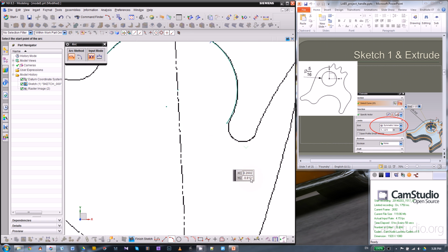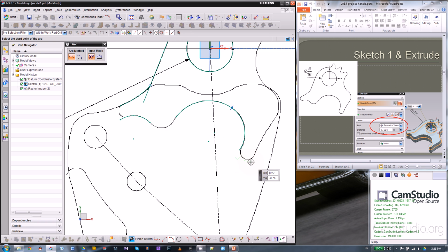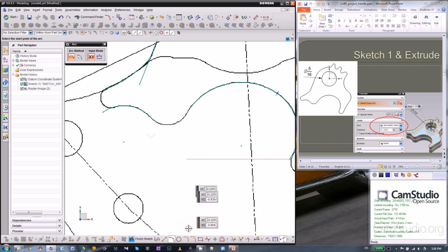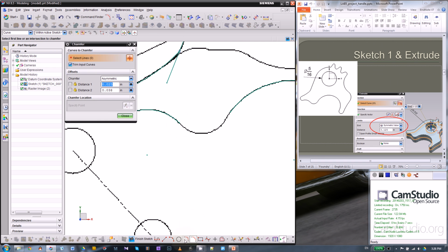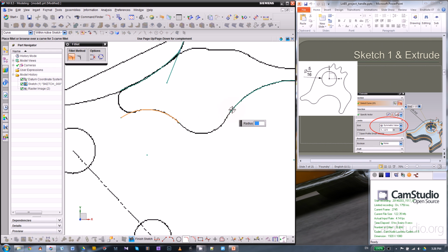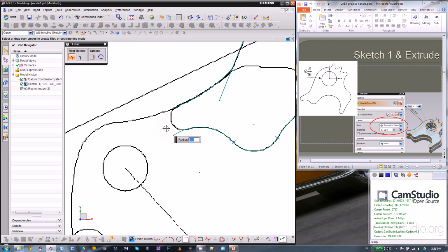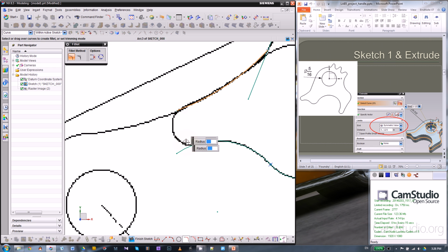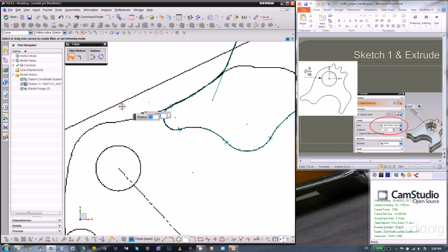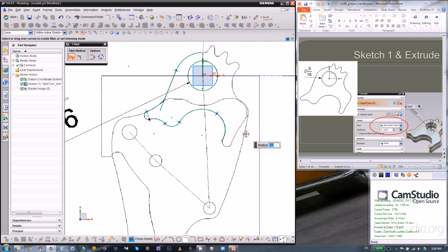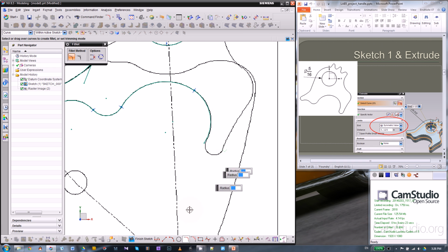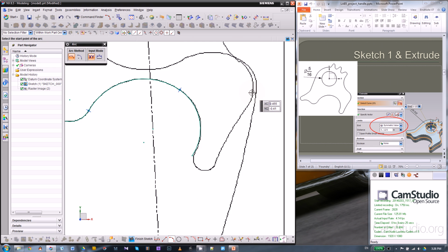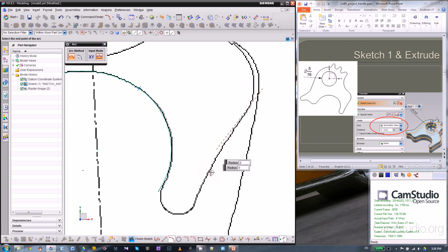Tangent is the best choice. If you cannot do that, that's fine. And for this, between the 2 arcs, I'll put in fillets, so it'll be tangent anyway. And also between these 2. Okay, so the trick is just skip one section, then use fillet between them.